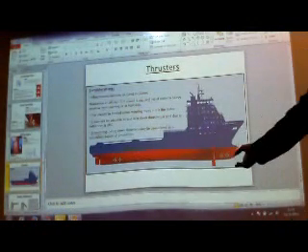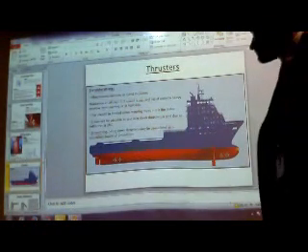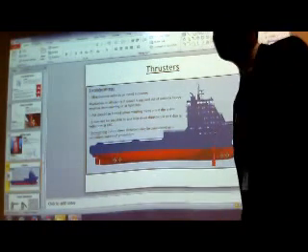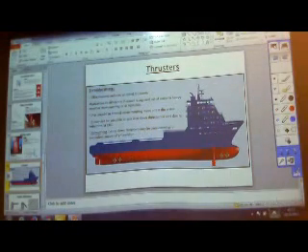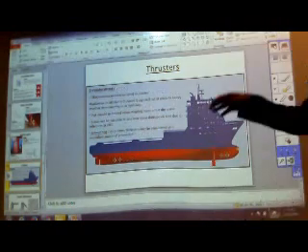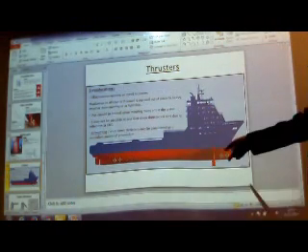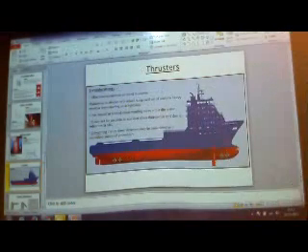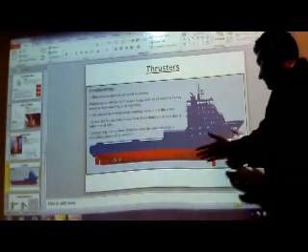Fixed pitch, you can see it, and you will see it on your bridge as well. Basically, they are fixed pitch propellers. Yes, but what is the design consideration? The flow of water around it, the linear speed of the vessel, the forward and aft speed. If your vessel is operating at a very high speed, this is going to be ineffective. There is not going to be enough flow around it.